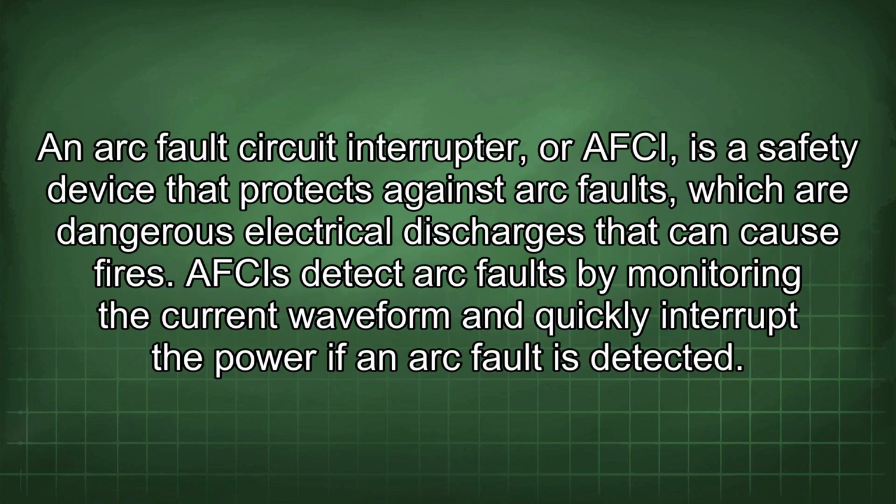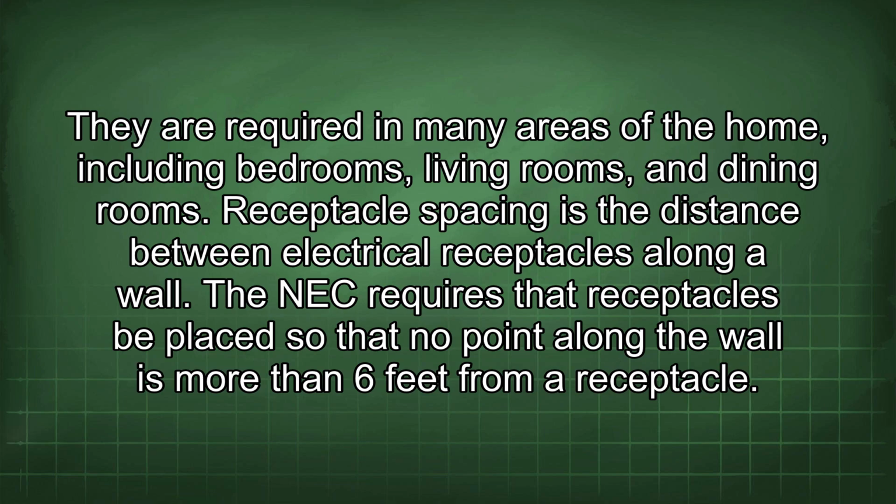An arc fault circuit interrupter, or AFCI, is a safety device that protects against arc faults, which are dangerous electrical discharges that can cause fires. AFCIs detect arc faults by monitoring the current waveform and quickly interrupt the power if an arc fault is detected. They are required in many areas of the home, including bedrooms, living rooms, and dining rooms.